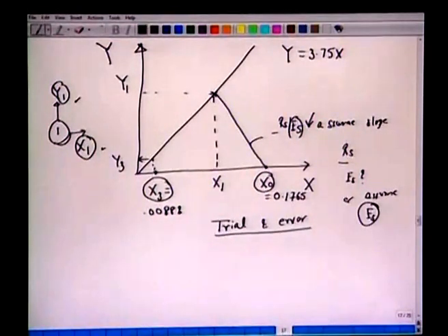Take this slope, we get this concentration x1. Now the second stage, again we are bringing this stream into fresh contact with the fluid, which is y0, given to us as zero concentration. If the amount is the same here and here, we will get the same slope. So assuming some value of Es, we draw this slope, we get y1. These two streams, y1 and x1, are in equilibrium, so we can mark this point x1.